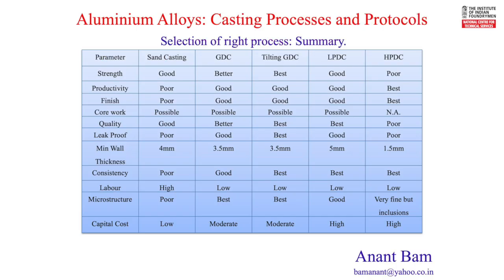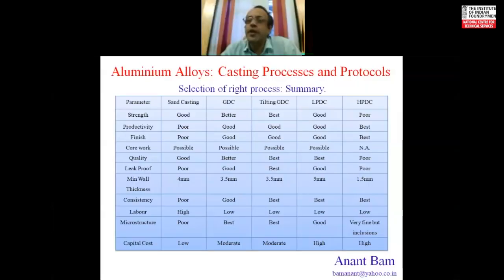It is very popular for structural pieces, structural elements, but for critical components, you have to go for further compromises. In case of any leak-proof castings, for high pressure die casting, impregnation becomes a process requirement. Usually we consider that impregnation is a salvaging process. But for high pressure die casting, it becomes part and parcel of the process itself. Because all the HPDC components are inherently leaking components. That is why I have put the word poor in front of quality.